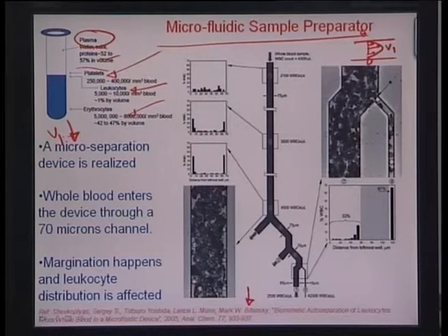And suppose you have a case where you are flowing through this end, through a pressure driven flow, a bunch of different cells immersed in a solution, one which is bigger, another which is smaller. Then what do you think will happen? The bigger cells would try to move towards the edges by the principle of conservation of momentum, because the velocities that they will encounter by doing so, at the edges, are much smaller in comparison to the velocities at the center. So automatically by the principle of conservation of momentum there would be a tendency of these bigger cells to marginate towards the sides, and smaller cells to come towards the center.